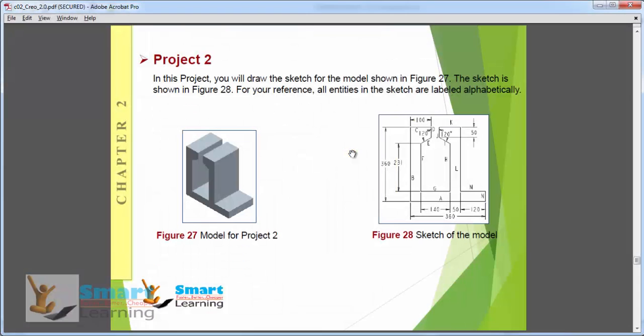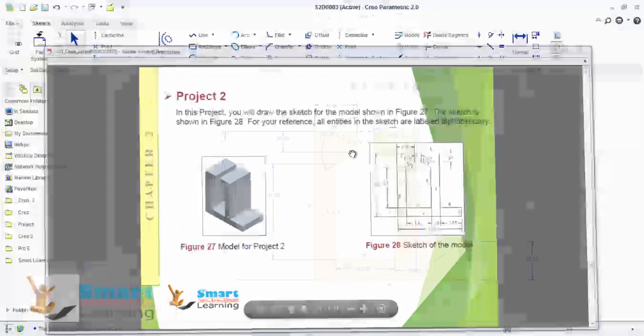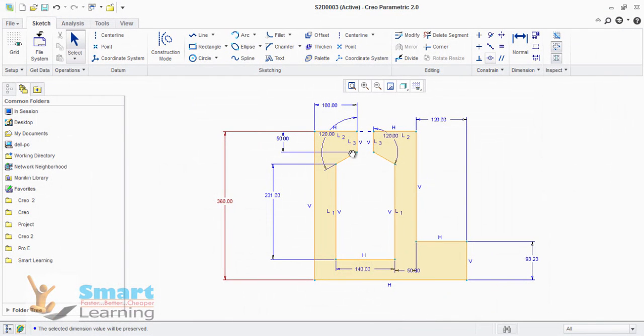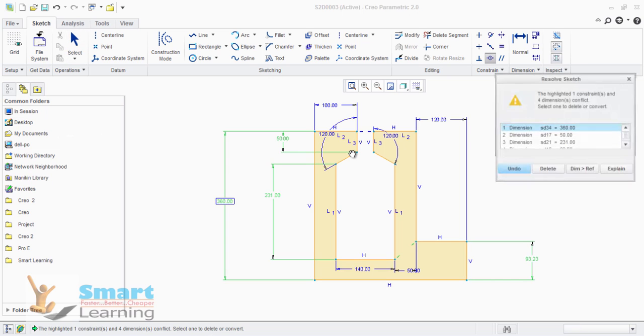And if you observe in our input drawing, you can see the lines G and M both lie in the same point. So here you can just click on coincident constraint, so you can just select these two entities.